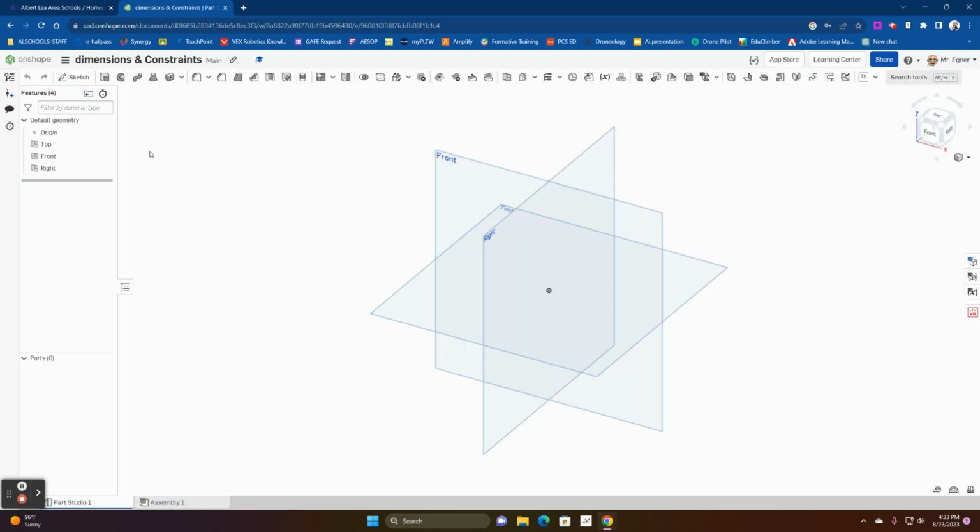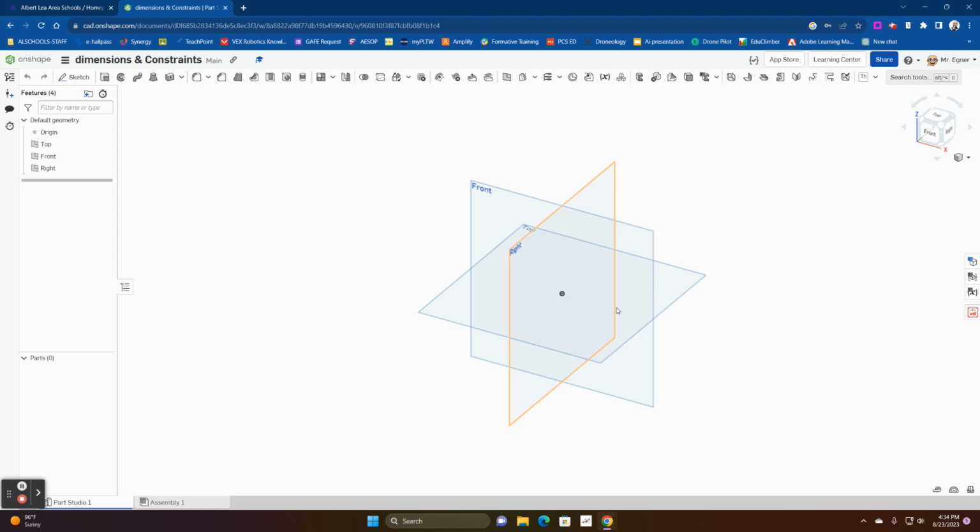Now, just to go over how we look at our toolbars across the top, we can see what we've got by hovering or holding over something. We can see the keyboard commands. So revolve is Shift plus W, and it tells you a little bit about what it does. If I scroll with my center mouse wheel, I zoom in. I recommend we use the button on the center mouse button to turn from free scrolling to the click so that you can feel it.